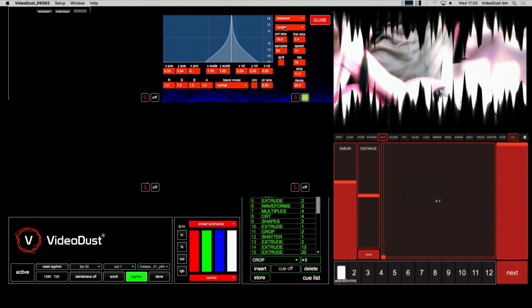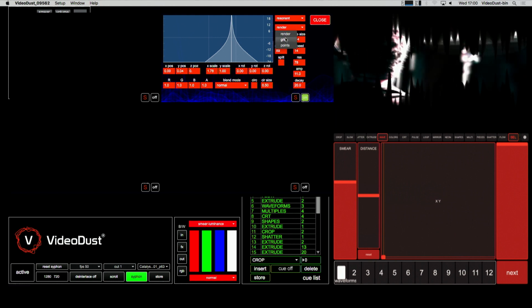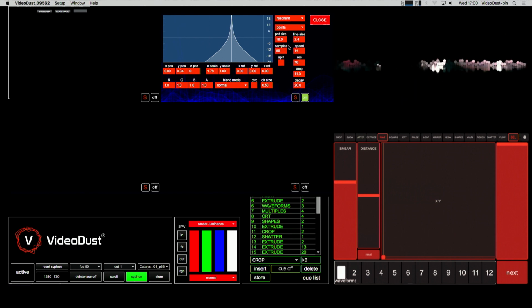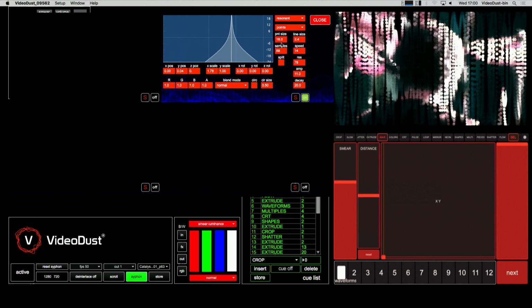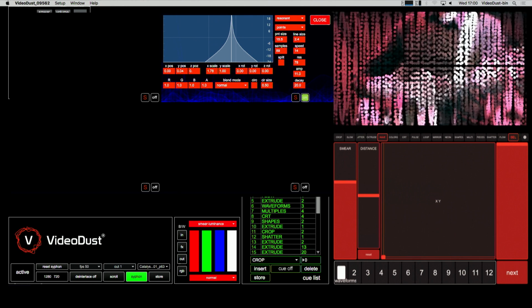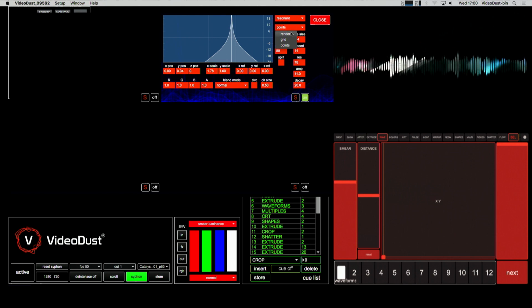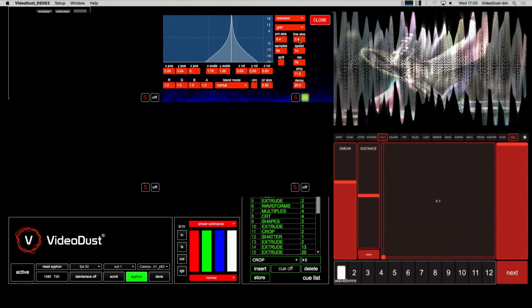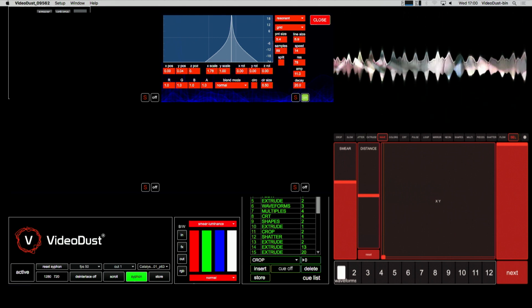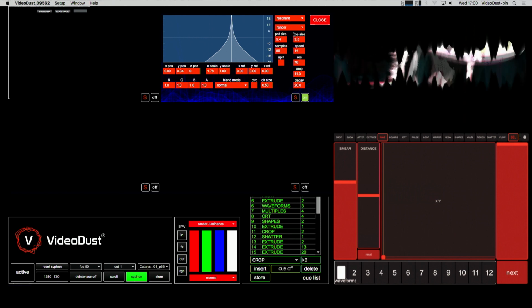And then below that you have your render mode. You have render, grid, and points. So if we choose points, this point size here is related to that. So if we change that, you're adjusting the size of the points in the image. And if we choose grid, your line size adjusts these sizes. Let's go back to render.